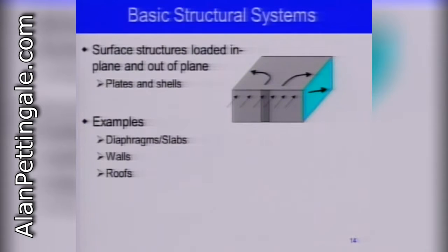This would be the diaphragm that holds the walls together, and its role is very, very critical in these structures. Let's say that you have high winds, so you would have this wall that is loaded with the wind, and that's a load that we call an out-of-plane load.